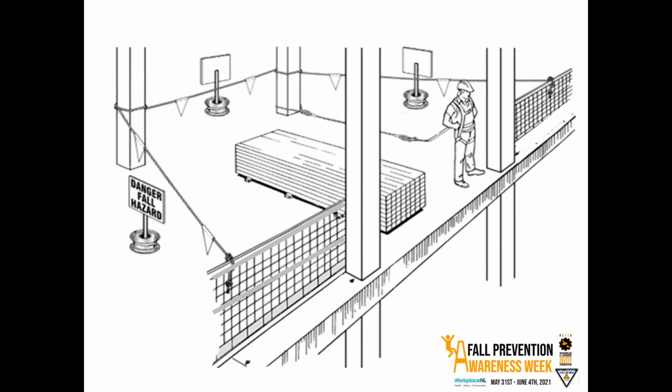So the next step to me is looking at, okay, the guy who's actually going to be working in that area. So step one, he needs to be tied off somewhere sensible. Again, we're going to assume that this is a brand new building. We got structural steel, we got maybe concrete columns full of rebar. Seems like a reasonable place for him to tie off or use as his anchor. We want him to be able to get near the edge of the roof so that he can grab the tag line for whatever load is coming up. Again, let's just say we're using a crane, so he can bring it into the safe space.